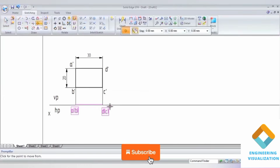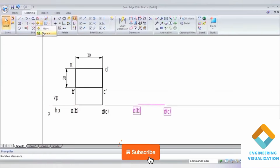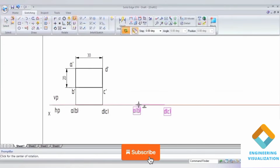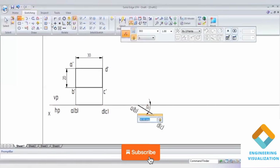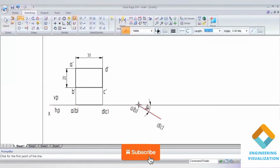Select the top view, go to the move command, create a copy of it and slide along the line. And now we can give the inclinations. So inclination to the VP. So here I'll give angle of inclination 30 degrees. Okay. So inclination below the XY line means minus 30 we have to give. Draw the projection lines to complete the second position front view.